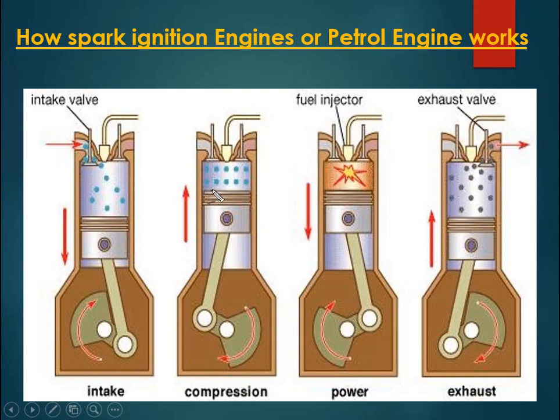So due to high pressure and high temperature, the fuel air mixture may ignite spontaneously without any need of a spark from the spark plug. This is called auto ignition. So during the upward movement of the piston, it may be possible that the fuel air mixture ignites prematurely. This is also called pre-ignition.